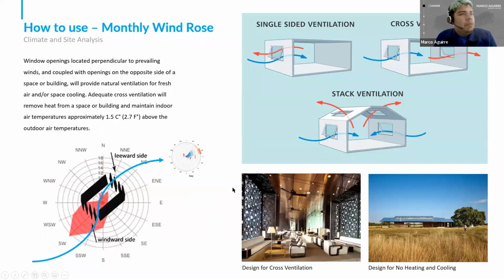Natural ventilation can be incredibly powerful. Not every project can have it. It's typically where you have more mild climates or tropical coastal areas, but it can be a huge energy saver as it reduces reliance on HVAC systems for cooling, heating, things like that. So identifying what the primary axis for ambient wind is, and then figuring out how the design can help support ventilation through the space. And of course, there's a lot of positive health benefits to natural ventilation in addition to reducing energy consumption.